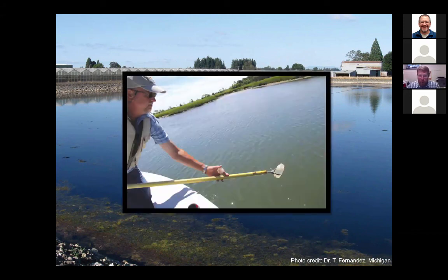For water quality sampling, we have a how-to guide I'll show you in a minute, but you should try to sample close to your intake depth and not near the shore where you see the algae building up in the bottom left corner of this slide. So you want to dip a bottle upside down, push it under the water to a given depth, and then flip it. At the surface, there's just too much biological and chemical reaction going on constantly to get a good read for what's going on.